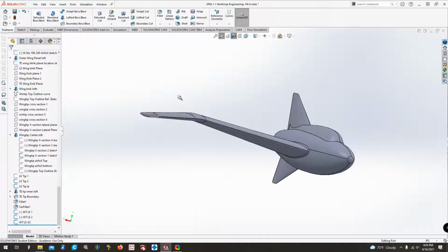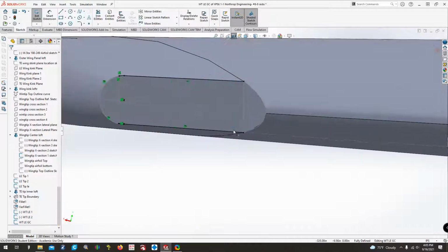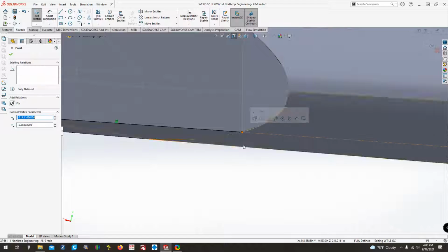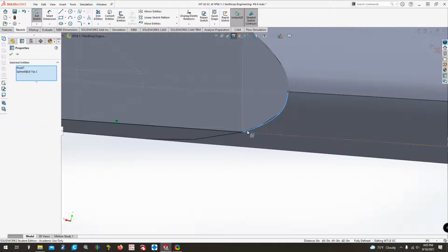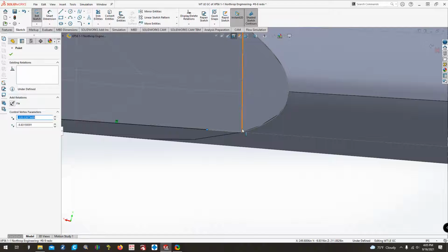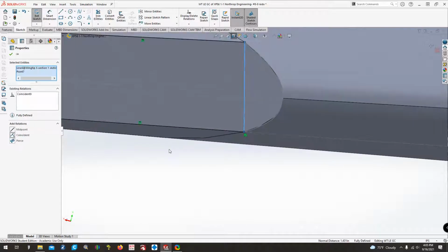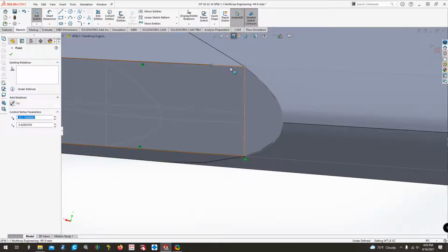Okay, well, we'll go back and fiddle with this stuff to figure out why it's not working. So this one here, select that point, and this spline. It doesn't like that one. Nope. Try this. Nope, doesn't like that one either. There to there. Coincident. Just drag it away to make it get to where you want it.